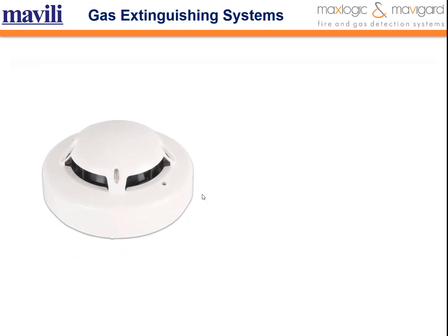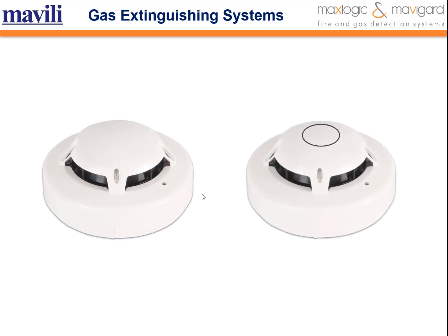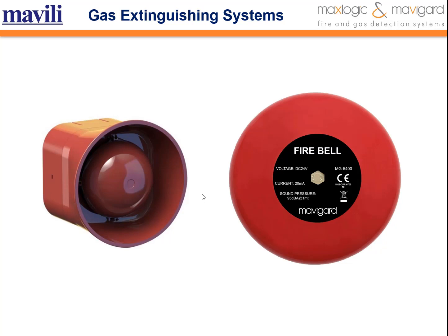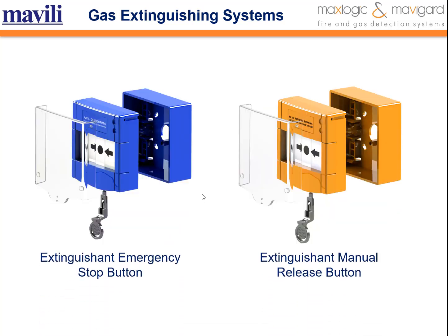And also, these are the systems that can be used with our extinguishing panel. These are the smoke and heat detectors we have. And we have a fire alarm bell that warns the user about the starting of the extinguishing. And also we have sounders and beacons that can visually and audibly inform the user that extinguishing has started. And we have extinguishing manual release buttons and extinguishing emergency stop buttons.